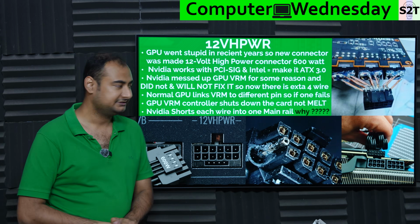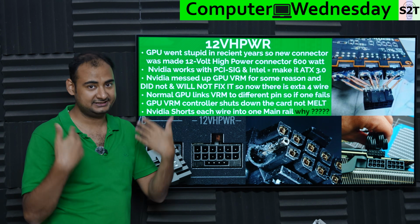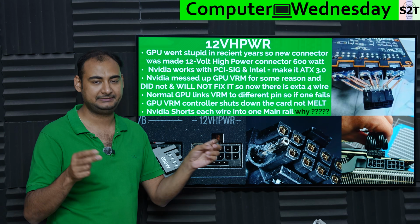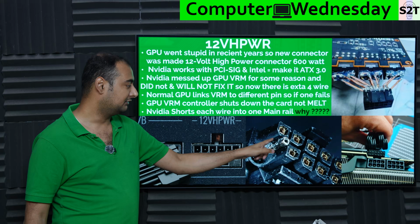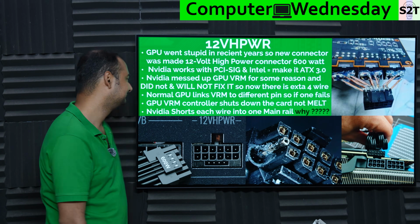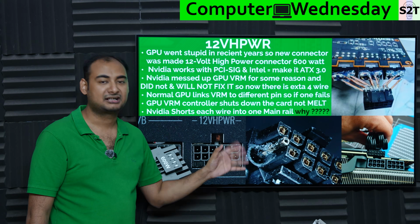So what Nvidia did is, they took the 12 pin that should have, ideally, been separated into 12 pins, or at least basically 3 pairs of 2 pins should have been separated. And in that scenario, if 1 pin was connected, others were disconnected, the VRM stage would be like, I'm not receiving voltage, I'm turning off. That did not happen. This was a gargantuan design fail.